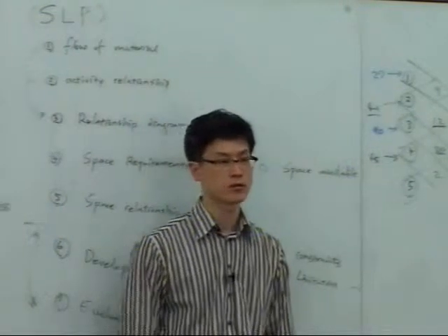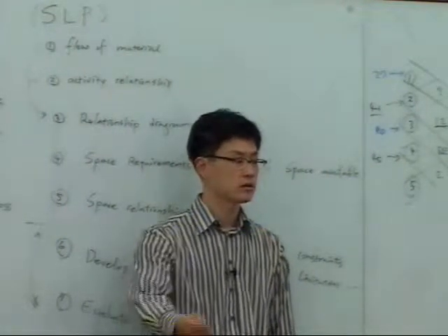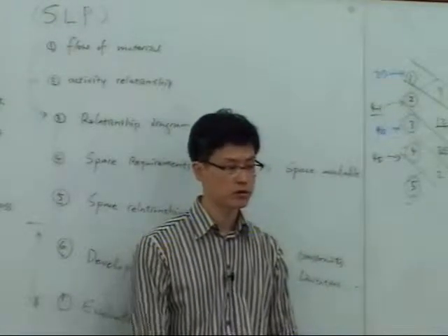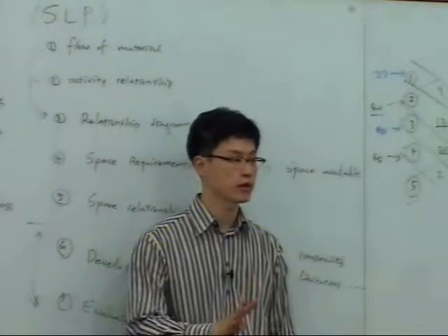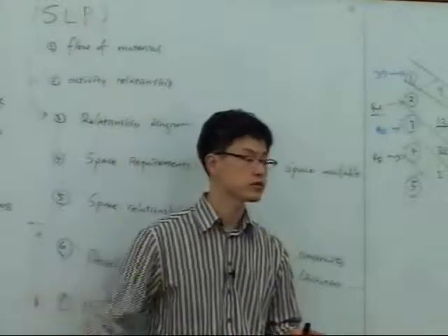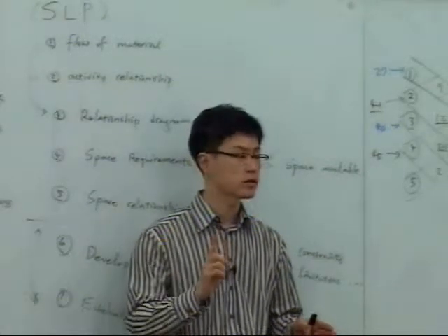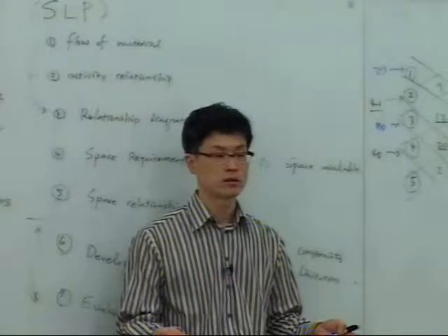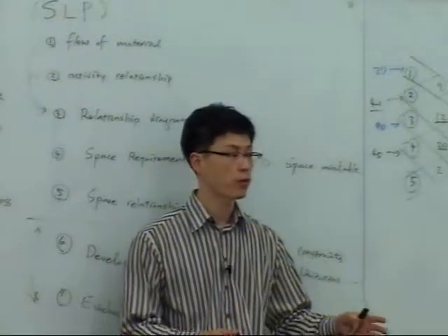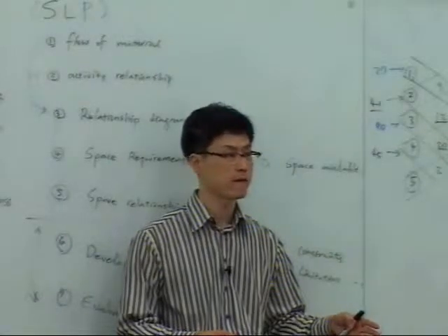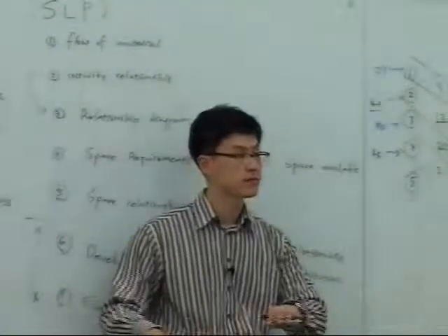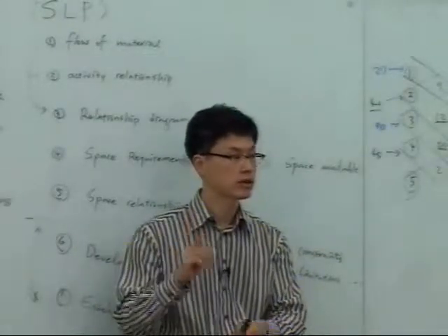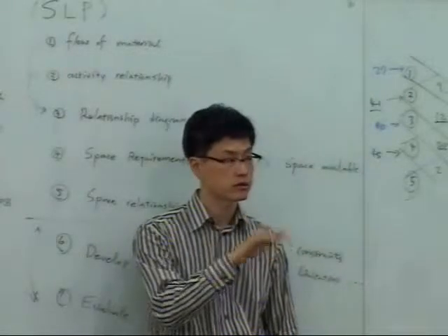Okay, let me give you an example. To do the process on the flat panel, you need 4 weeks. But your customer, the next workstation, requires one panel every week. Then, at least you have to have 4 work pieces at the same time, right? Because cycle time is 1 week, lead time is 1 month, 4 weeks.